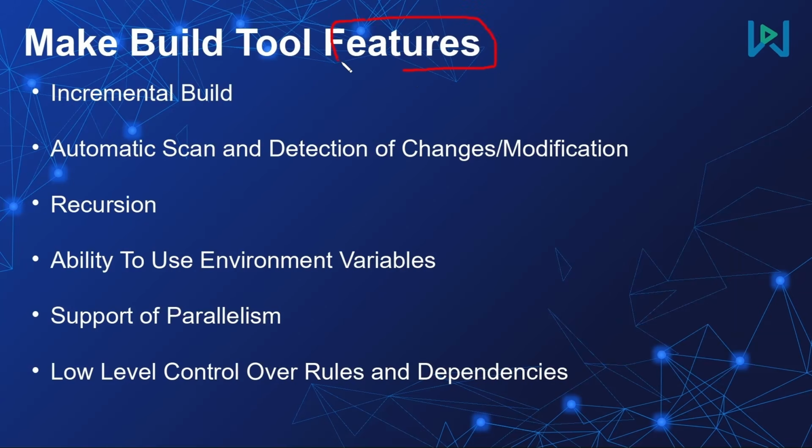Before tackling the different features supported by our Make build tool, you will need to distinguish between the Makefile and the Make build tool itself. The Makefile is just the file that will embed the syntax and set of rules to automate the flow of compilation and building of our embedded system project. However, the Make build tool is the tool itself that will be able to parse this file and execute those rules.